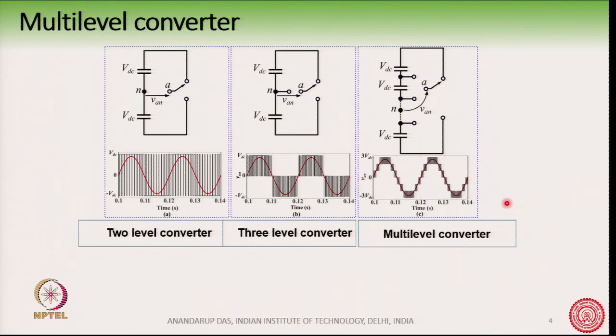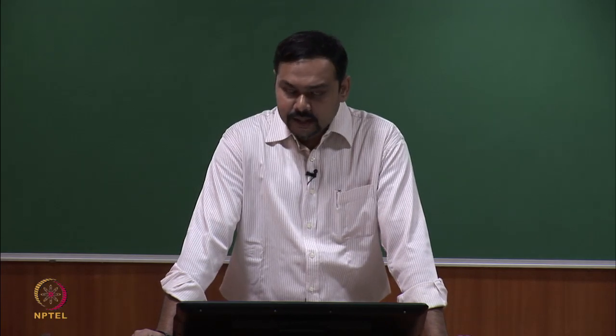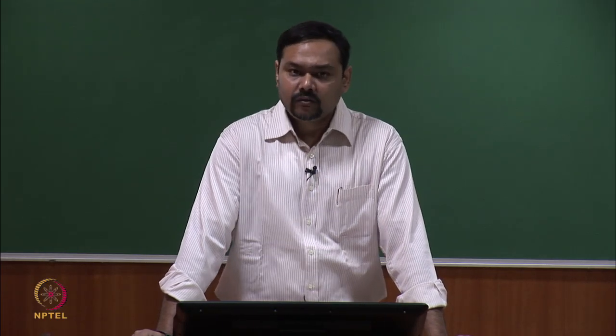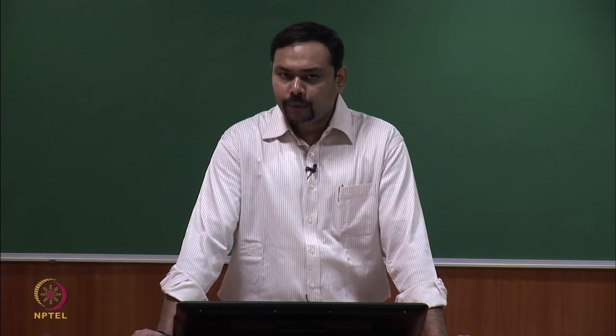Okay. The motor and the cable inductance is sufficient to attenuate any high frequency currents. So, we do not need any filters, and this is the reason why multi-level converters are popular.